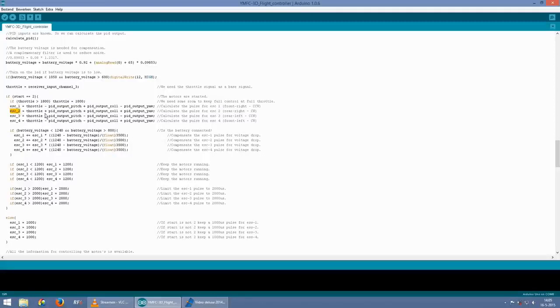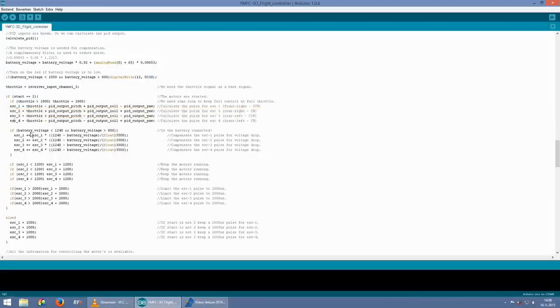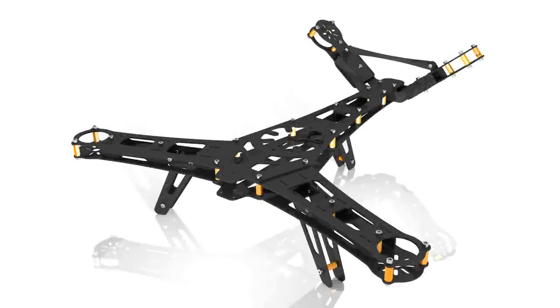Its pulse is a combination of positive pitch PID correction and a positive roll PID correction. And we do this for every motor/ESC combination. Now all the motors are at the same distance and angle, so we don't have to do special calculations. But when needed, you can calculate your own multicopter layout this way.